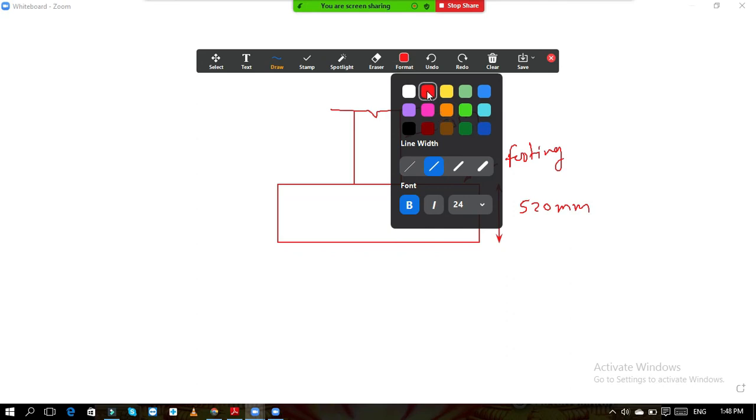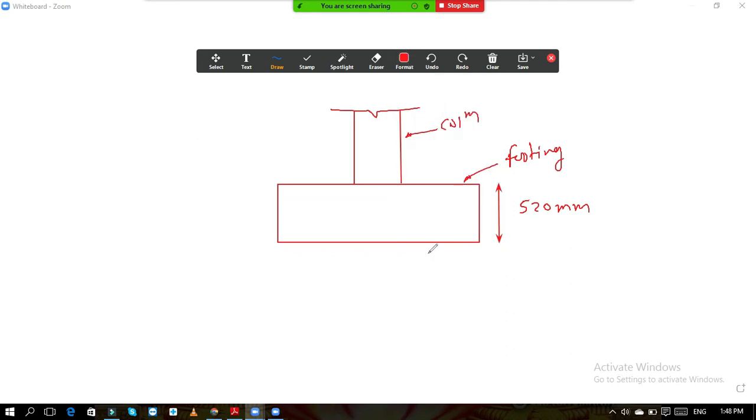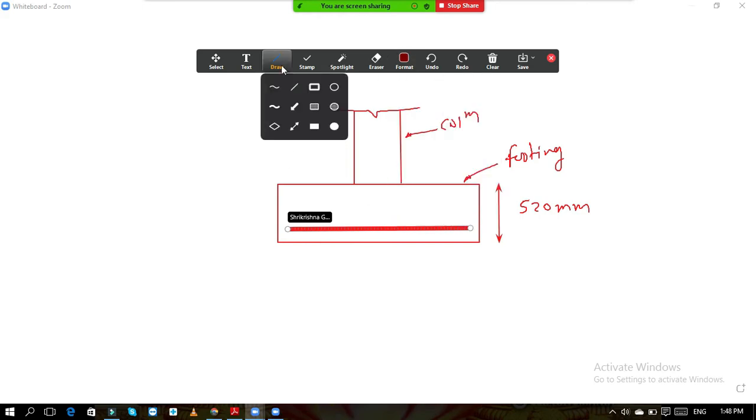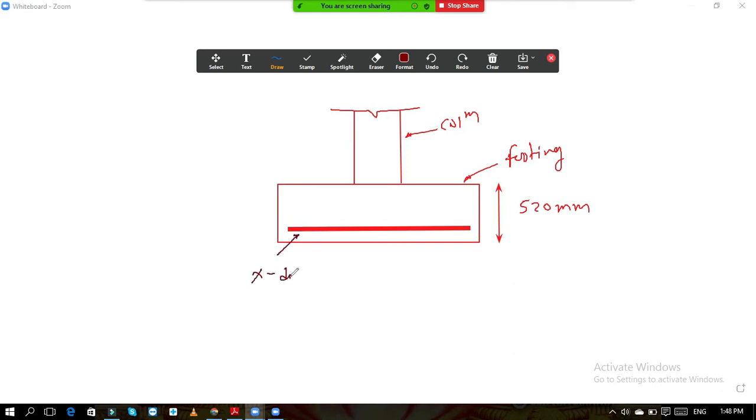Now by lifting some clear cover, okay, on both the bottom and on left and right side, we have provided one bar over here, this bar, and this is your steel in X direction. This is the X direction steel. And what was it? This is 16 mm bar about 160 mm center to center in X direction.